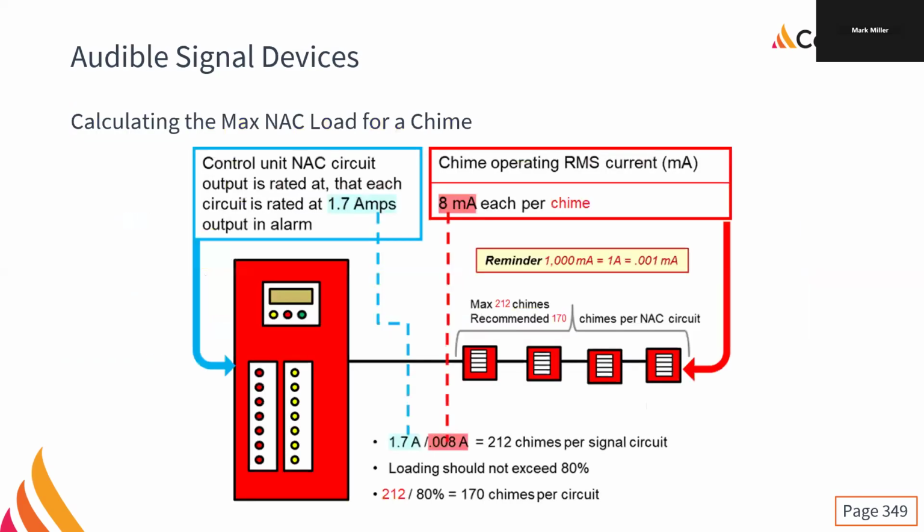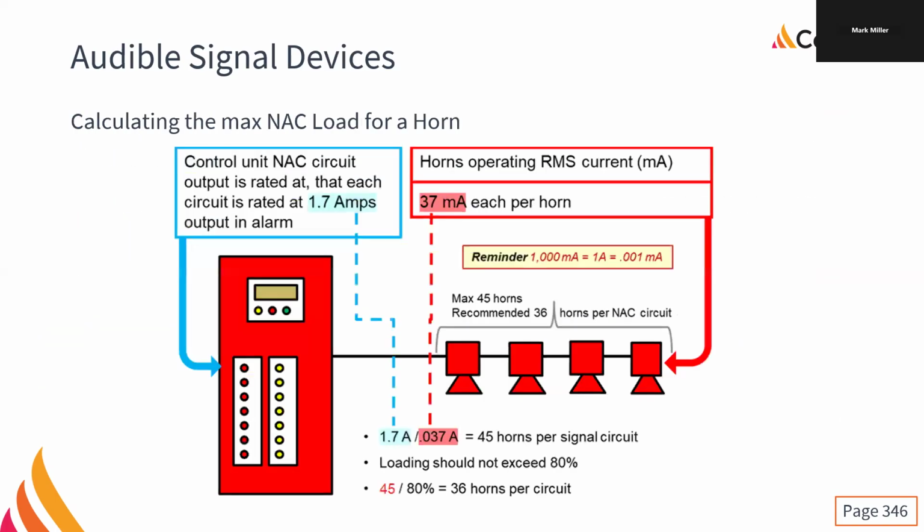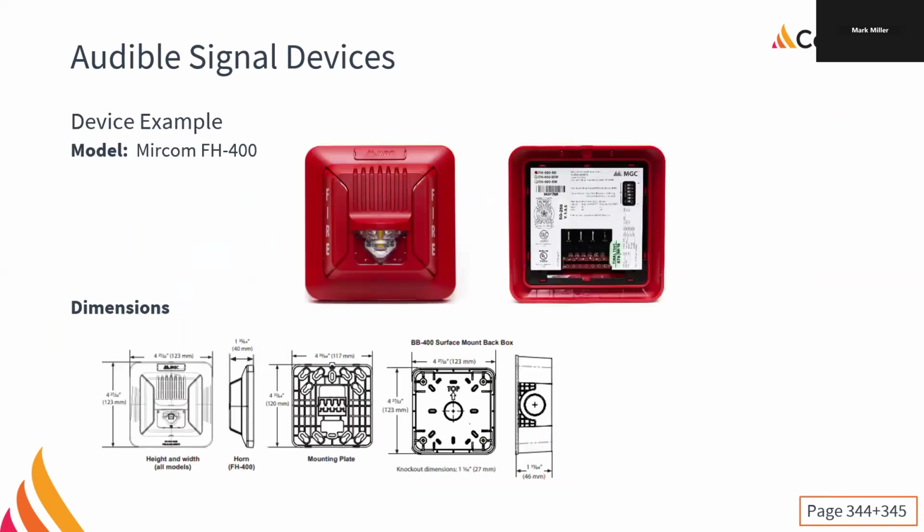If we go back a little bit, this horn gets mounted on a 4-inch square box. Great. So we make sure the top of that 4-inch square box is at least 150 millimeters down from the ceiling, and we're going to be good. If we put it exactly 150 millimeters down, that means we're going to put it 27/64 of an inch too high, right? So pretty close enough. If you're getting that close, there's only so much you can do.